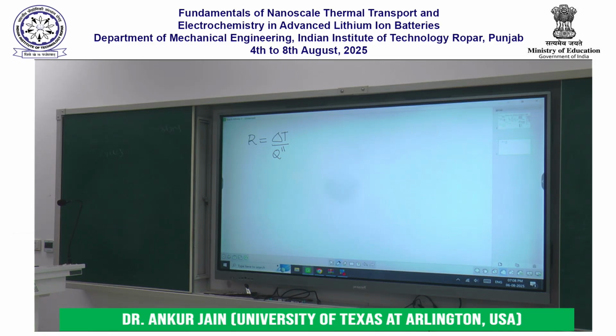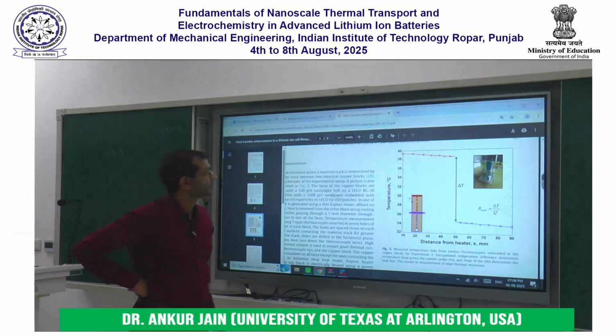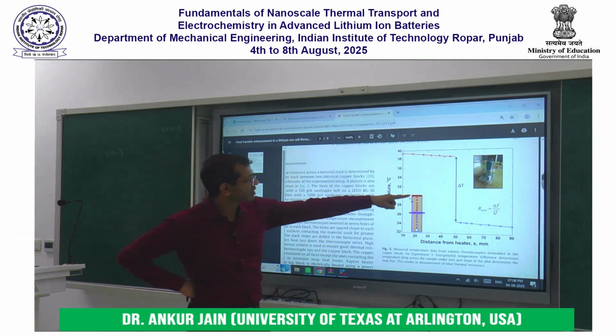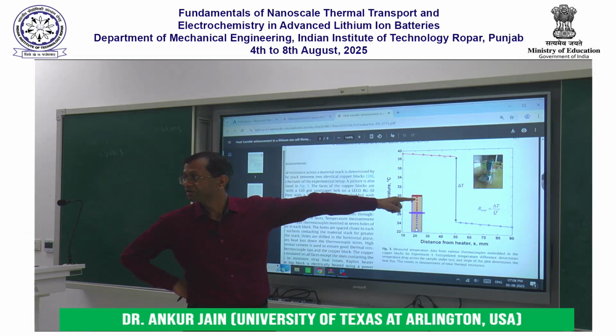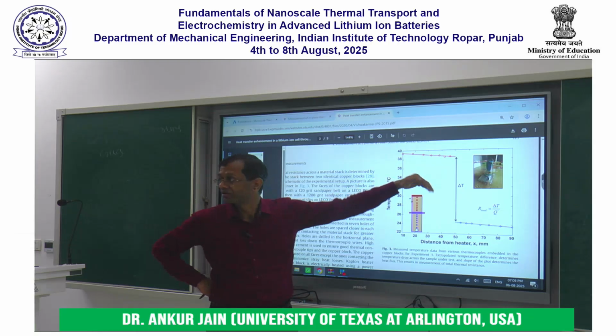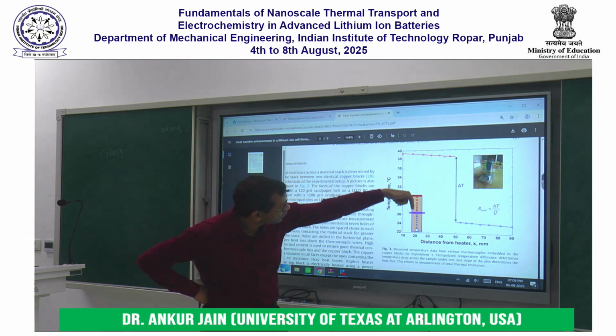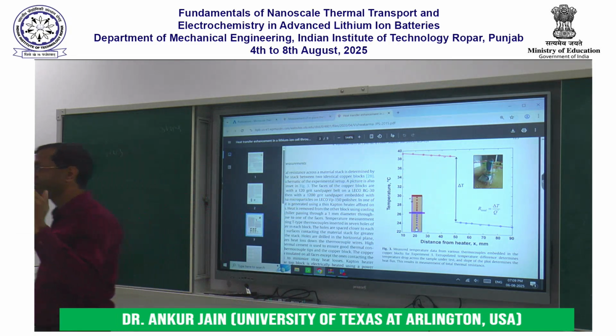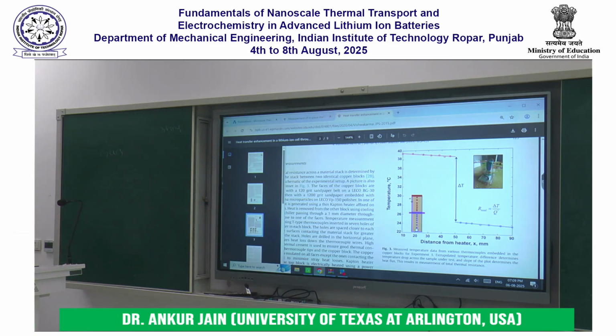Sure. There are a few ways of doing that. If I measure how much current is passing through my heater and if I have reasonably insulated around it, then the amount of heat passing downwards is equal to the heat that is being generated in the heater device, right?